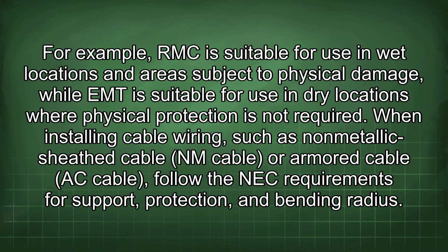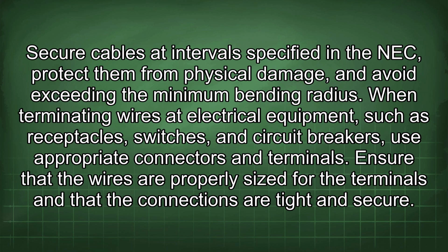When installing cable wiring, such as non-metallic sheathed cable (NM cable) or armored cable (AC cable), follow the NEC requirements for support, protection, and bending radius. Secure cables at intervals specified in the NEC, protect them from physical damage, and avoid exceeding the minimum bending radius.